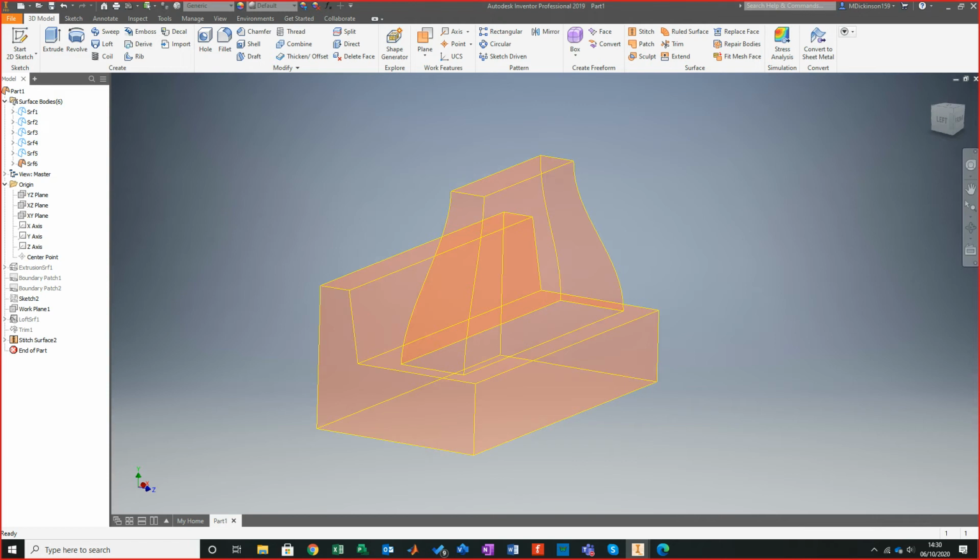But either way, what I've now got freedom to do is simulate in those two configurations. If I try to simulate with a solid base structure, with a volumetric structure, it's going to be problematic, because the second I put it in, it's going to find problems. And volumes, what you essentially say to systems is, I'm going to let you decide the non-linearity of these volumes based on these equations which already exist. Hence why you use what they call shells.